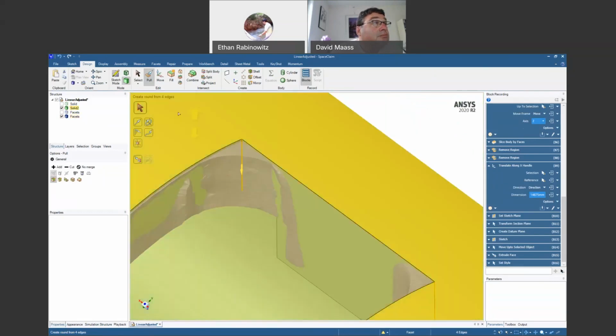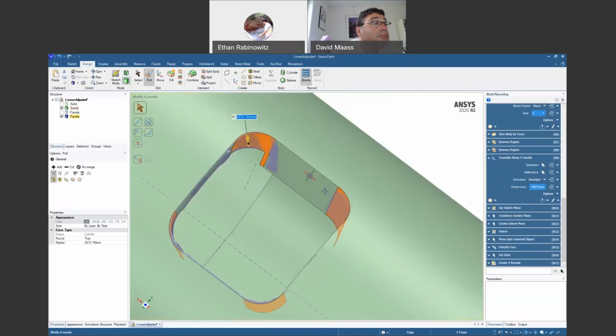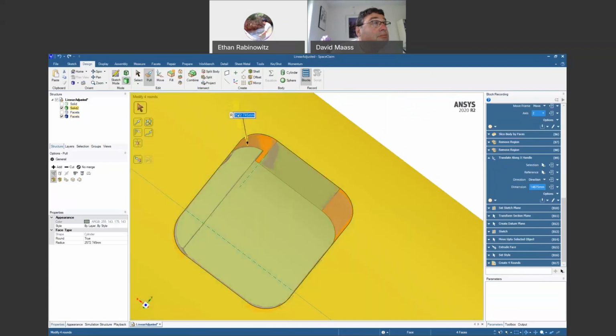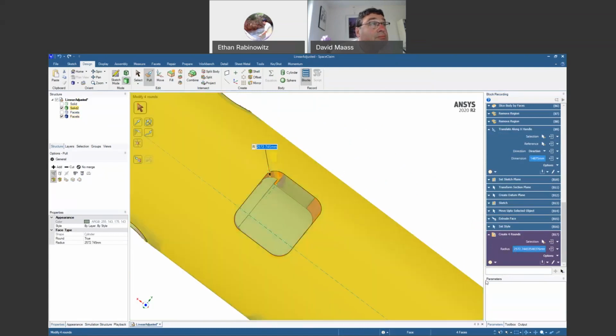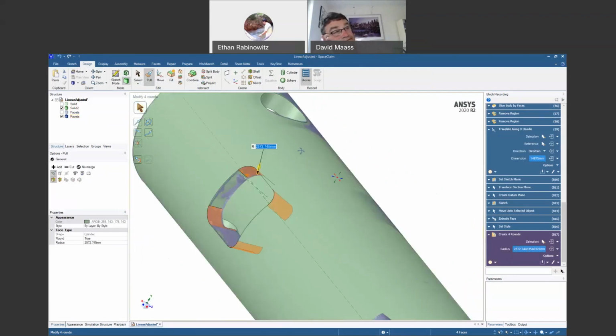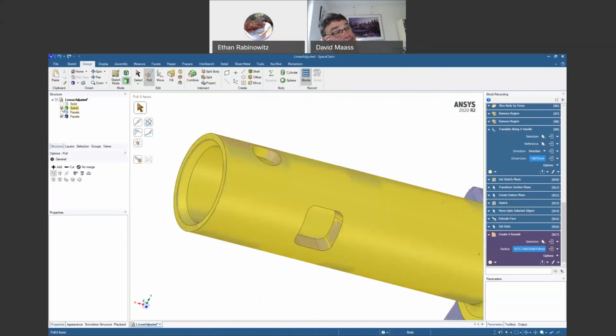So we'll say we have those edges selected. We just say up to, pick a facet here. And now all of those are rounded up to that. Of course, if I want to adjust this, what you should do is come in here and edit it in the block panel. If I actually edit it in the GUI, it will add another modification to it. So anytime you want to tweak a value as a result of a pull like this, you want to come in and do it in the block panel. All right. So that one's made.